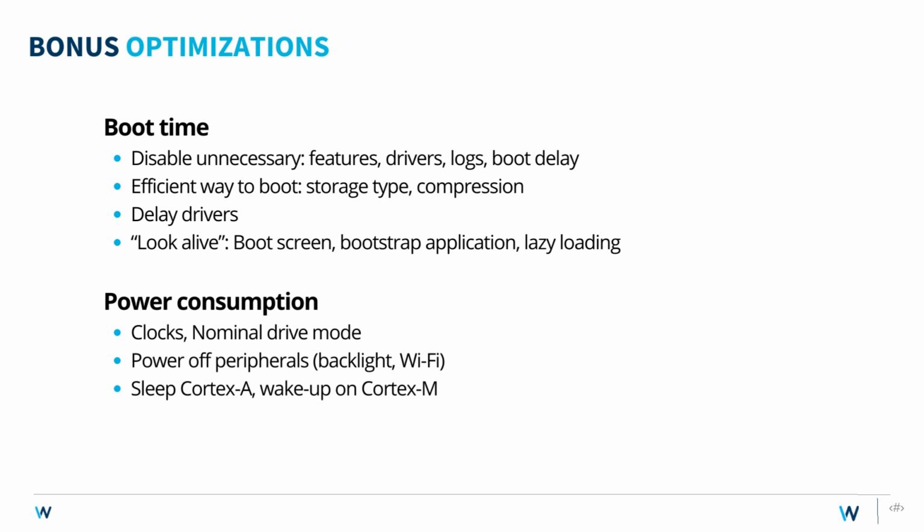But some of the things you can do to reduce your boot time: removing unnecessary features. So we're talking packages, we're talking drivers, we're talking logging. That actually takes a lot of time. And the boot delay that you have typically in your boot.